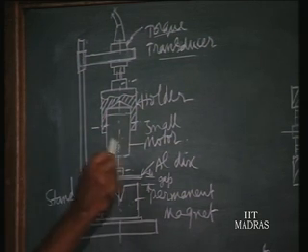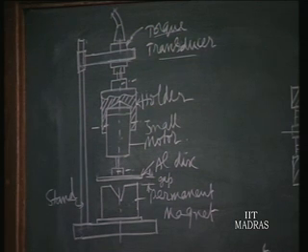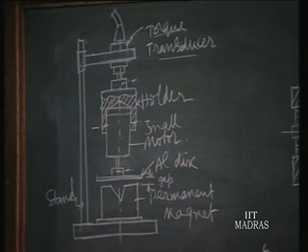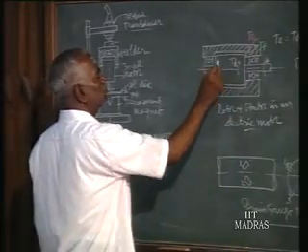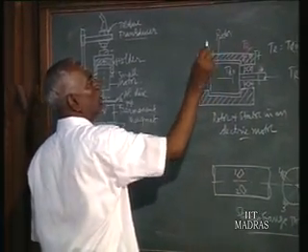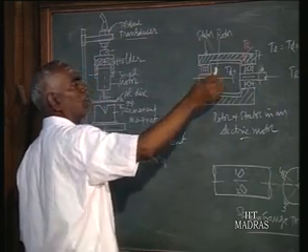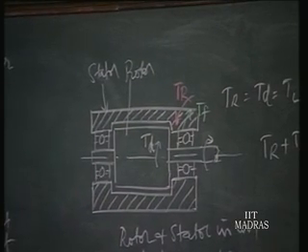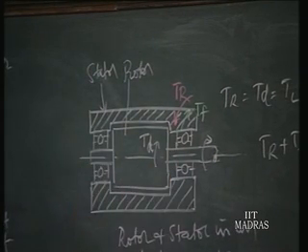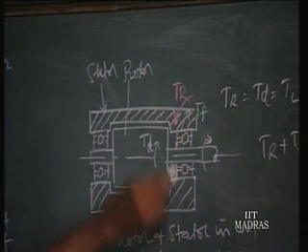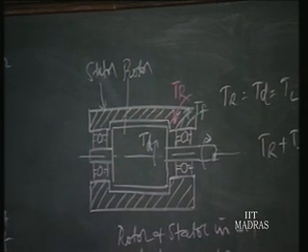Now when we are measuring the torque at the stator, does it include the friction torque? Because we know the rotor is mounted in the stator by 2 ball bearings like this. It is shown here. This is the rotor and this is the stator. The rotor is mounted inside the stator by 2 ball bearings. So when we measure the torque at the stator, does it include the friction torque which is being dissipated as heat? That is the question.